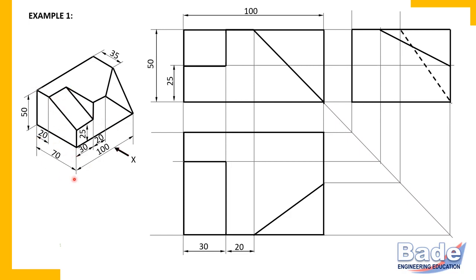No. Now let's focus on dimensions parallel to width. So overall width 70, but before that smaller dimension parallel to width, that is 20. There is dimension here 35 also, and then largest dimension 70, that is overall width of the object. Okay, so 20 millimeter. In the top view width is, in the side view also width is. So in the top view we will prefer.